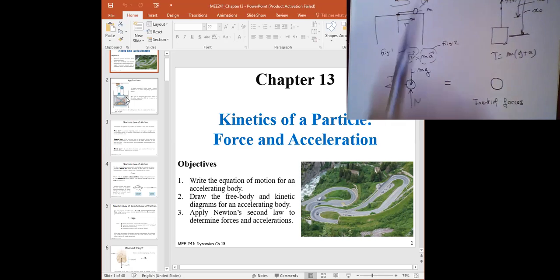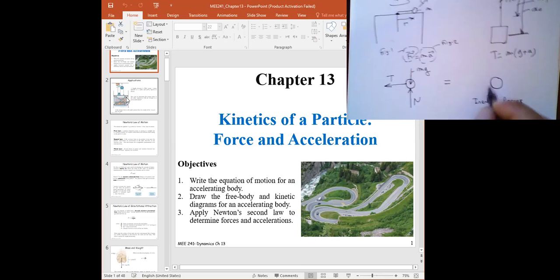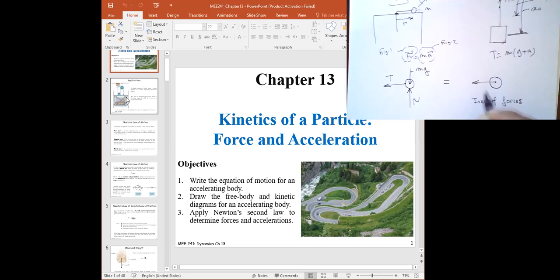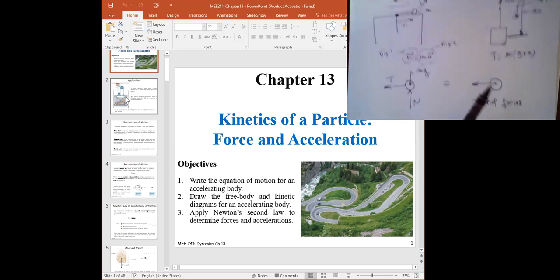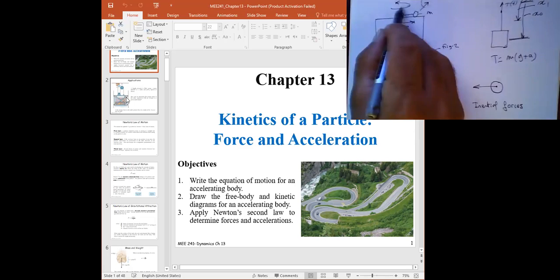So this figure is actually drawn in this plane, in the plane of the paper here. So what acceleration are we going to have? MAN only, because this guy is rotating in a circle. So the only thing that you can have is an acceleration toward the center of the circle, which is along this direction.